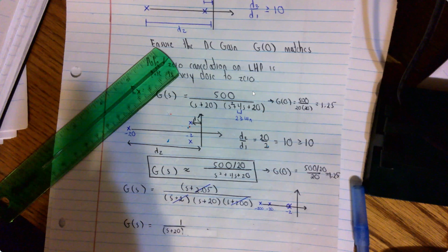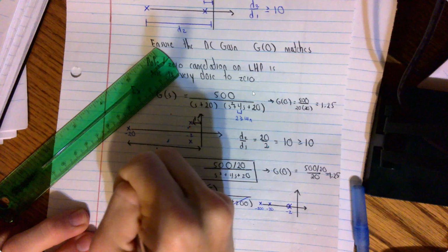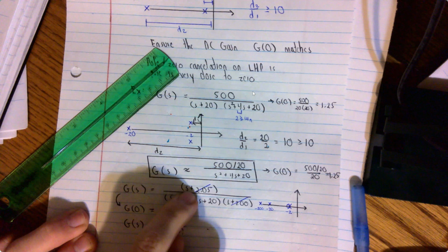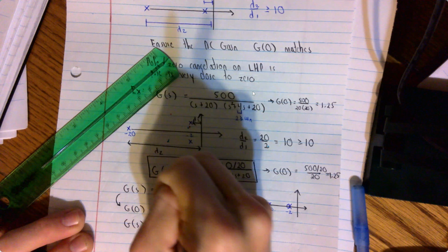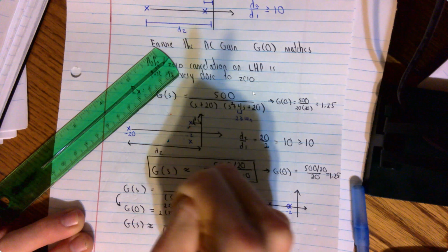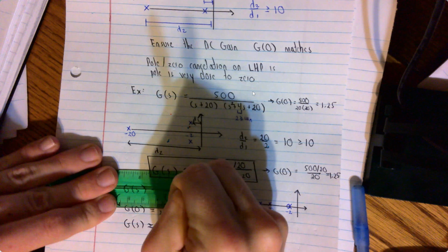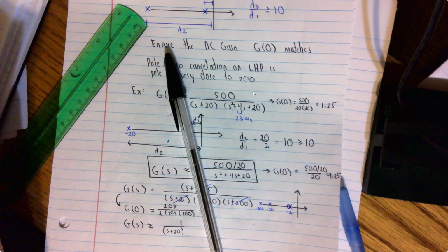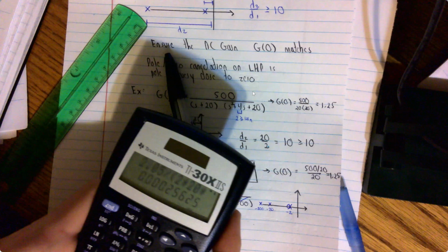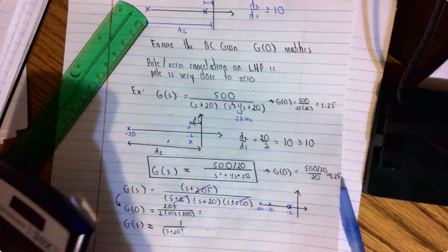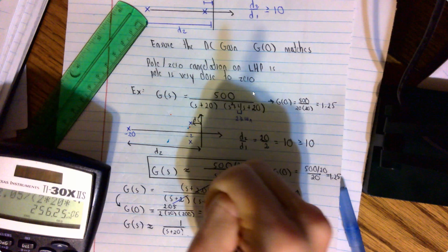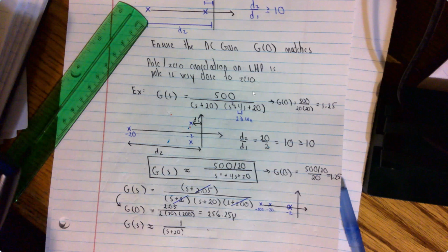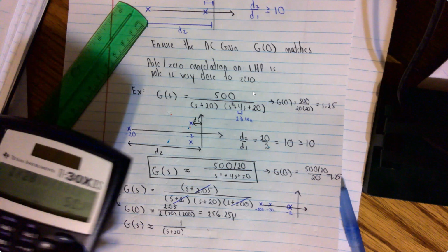And so now we need to make sure the DC gain matches. On the original system, our DC gain was equal to 2.05 divided by 2 times 20 times 200, which, if we look at that on a calculator, is approximately 256.25 micro, whereas here we have 1 divided by 20, which is only 50 milli. So we have to make sure the DC gain matches.